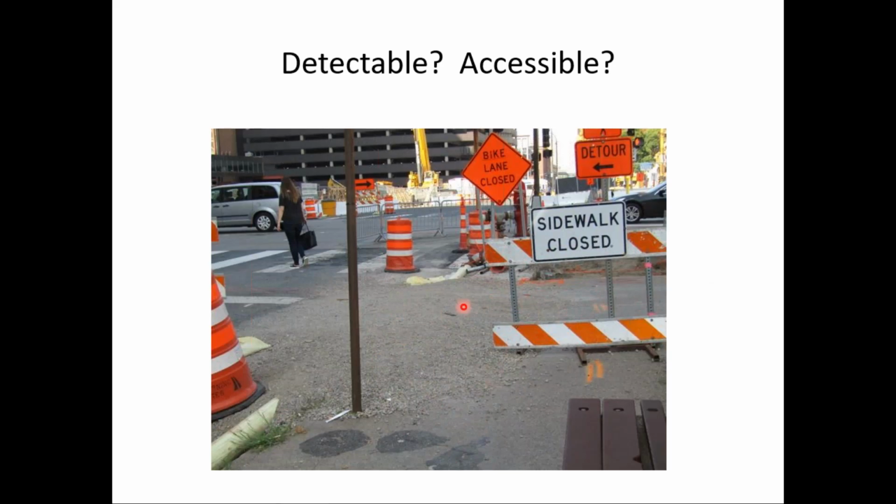So vehicles and equipment would use that kind of driveway. You can see it looks like there was a water pipe in the gutter here, and to allow vehicles to pass over that pipe, they put in some pea gravel. But pea gravel and wheelchairs don't really mix. The wheels of a manual wheelchair would probably quickly bog down in that pea gravel. So this is not accessible either. Someone in a wheelchair could not get through that path there.